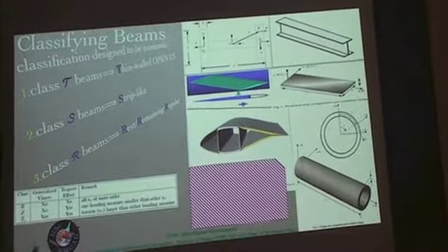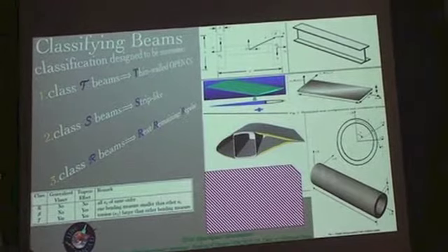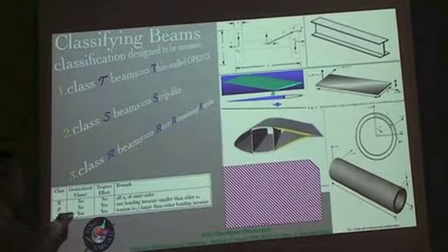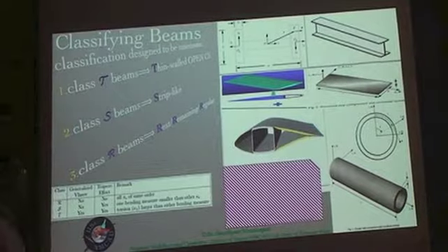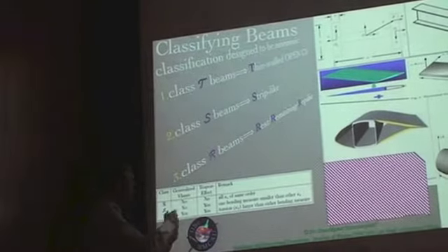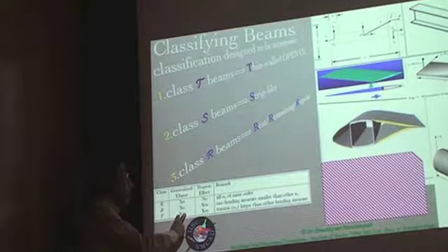On the other hand, for thin-walled open cross-section beams, the kappa 1 prime or the restrained warping effect becomes really critical, especially for I section beams. It is very, very important. So that has to be included.